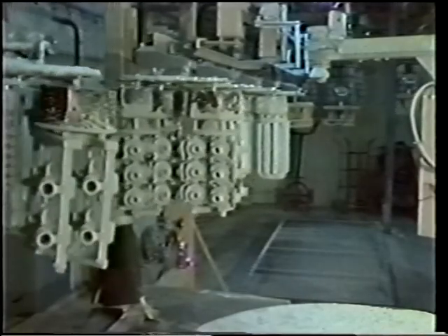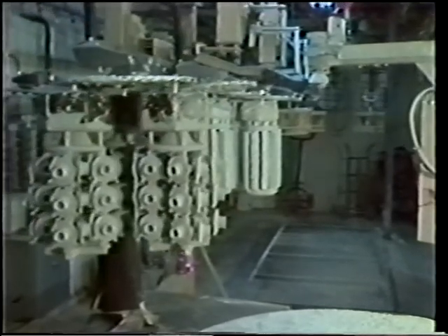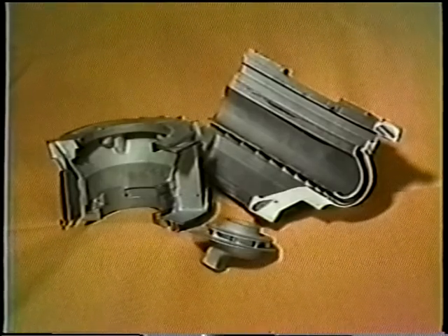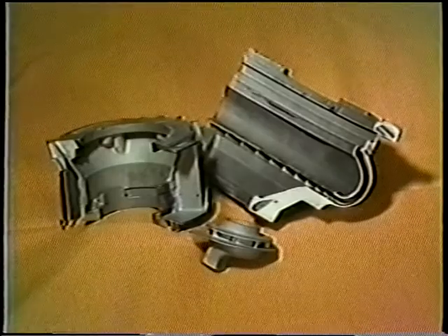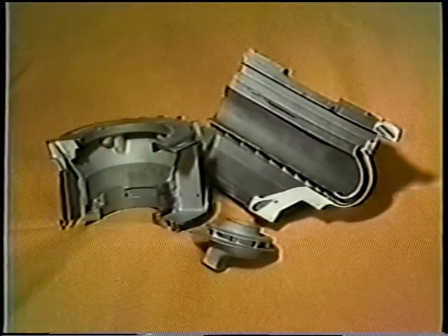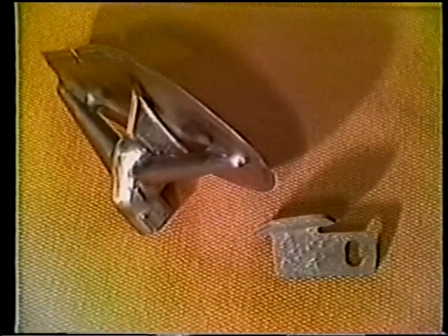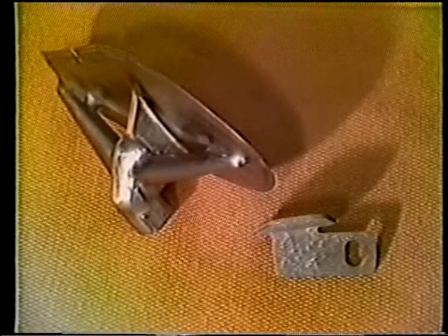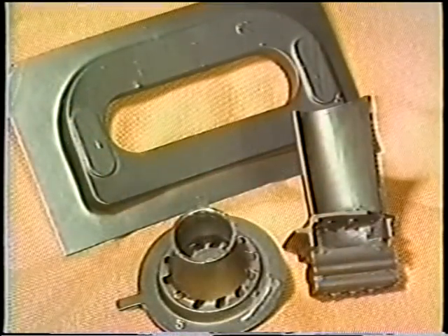Though investment casting is generally more expensive than other casting processes, the use of an expendable mold has many advantages. Due to their non-symmetric or intricate shape, many parts cannot be cast by other processes. Oftentimes, these shapes can be cast using investment casting much more economically than they can be machined. Since no mold material must be packed around the pattern, very thin sections can be cast. Very close tolerances and good internal quality can also be maintained. Due to the nature of the ceramic mold, excellent surface finishes can be produced as well.